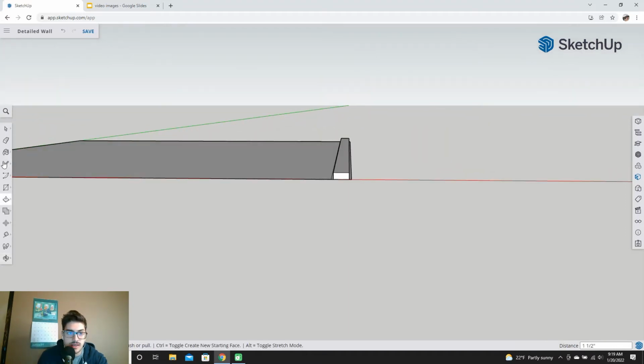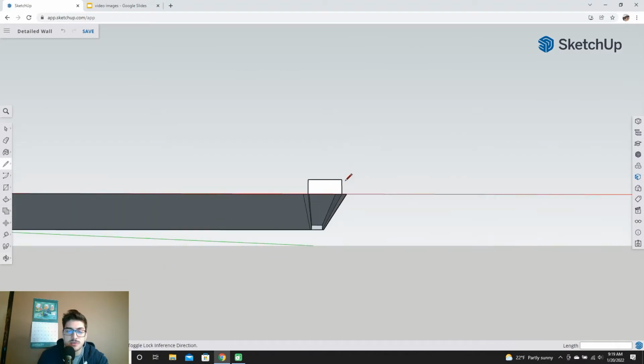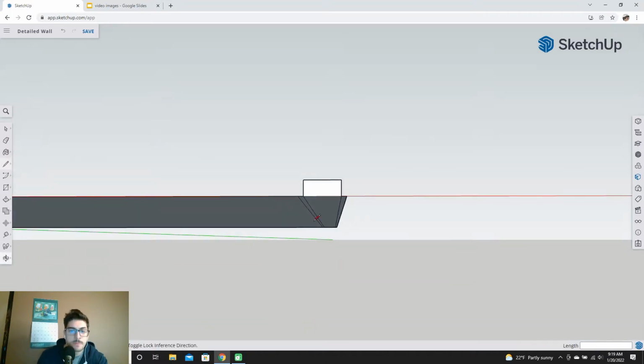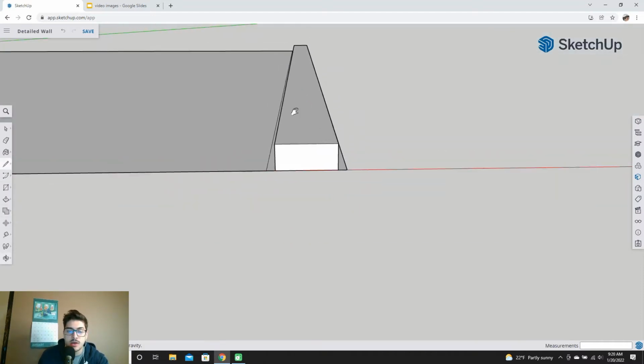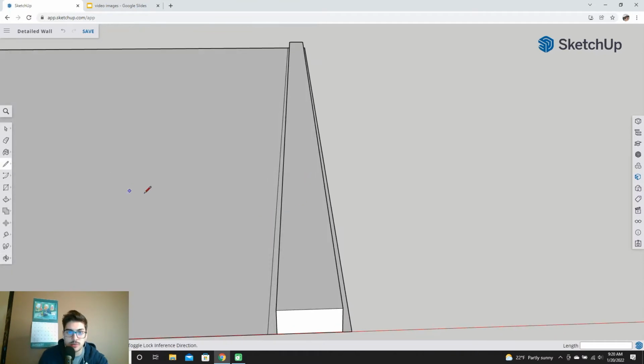And you can see, if you've dealt with 2x4s before, this clearly looks like one. You may notice when you extrude stuff that the backside of it can become empty. The way you fix that is just grab your pencil tool and, on any one line of the hollowed out shape, draw that line again and it'll become solid. Okay, so now we have a 2x4 just sitting on the floor where it would actually go.